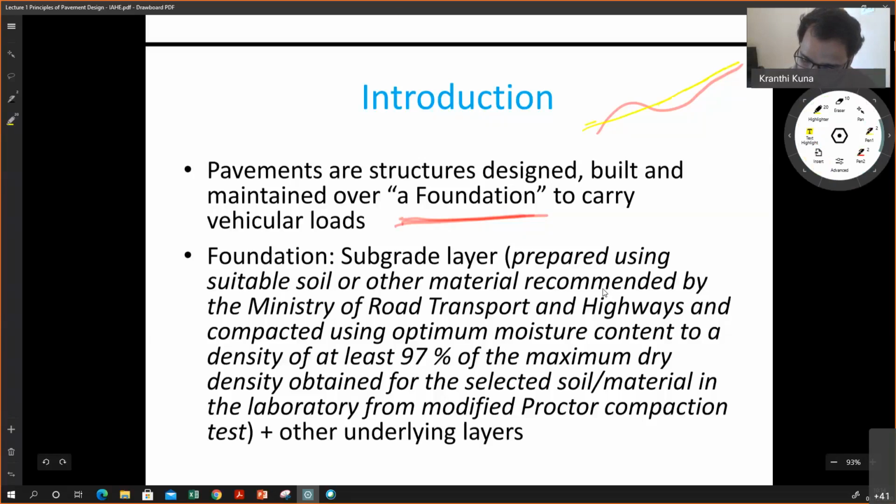Okay, so I assume this is your geometric design profile you developed based on geometry. This is existing topography. You will cut this, and you make use of this material and fill here. So this is cut and this is fill.